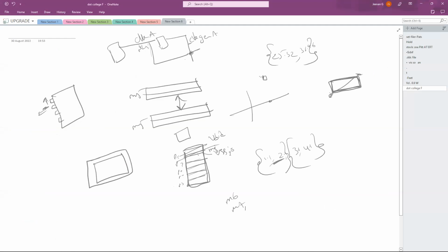All this information you can get through the physical libraries only. See, logical libraries mean timing related information or logic information. Physical means everything: height or width or area, the space where it got placed, and with respect to the metal layers, the distance between metal layers. The space that should be there within metal layers, the maximum width of metal layers, everything comes under physical libraries.